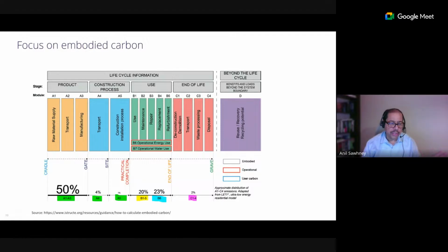But again, it's pretty straightforward. If you're running an excavator for 200 hours, every hour there is this much emission, you multiply it by 200, and let's say you're using 5 excavators on site over a period of 2 years, you will then be able to calculate your emissions. Right? Make sense? Yes, sir.